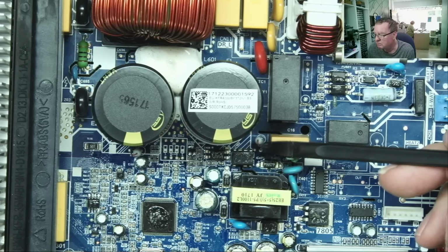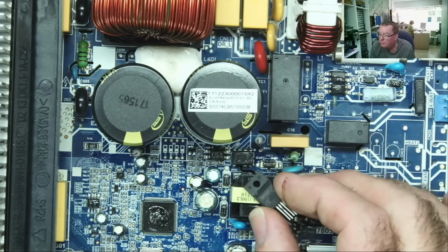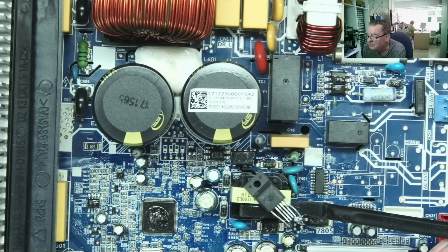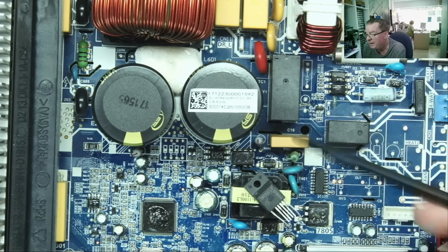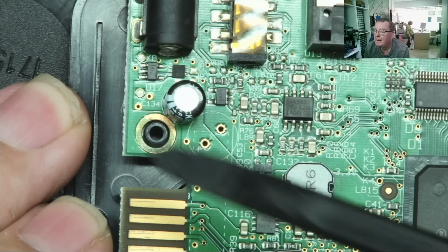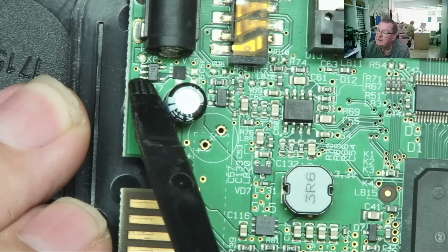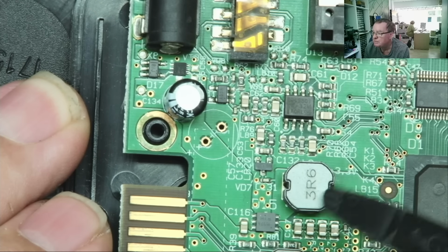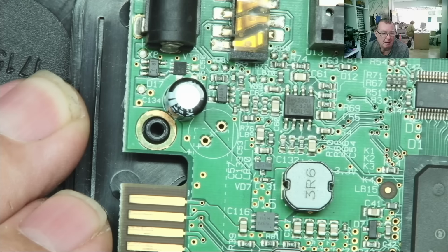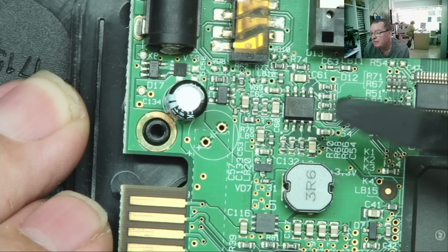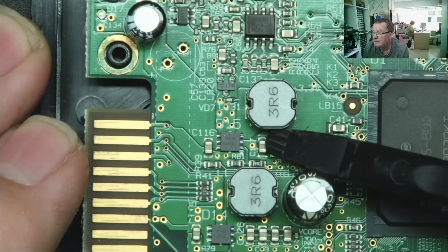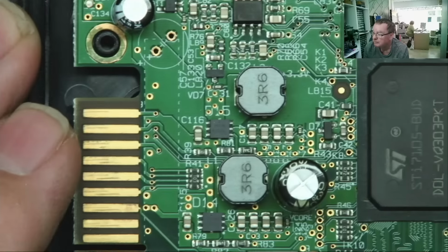There's another common style of these, which are these type of devices, again commonly found in standby supplies, or they could be the main supply for a low powered item, as could that. And surface mount devices like this one we see here, another one here. These are quite commonly near to an inductor coil. These are also power devices. They are DC to DC converters, and these again are fairly common failure points. Sometimes they will also look like that one you see there and there.